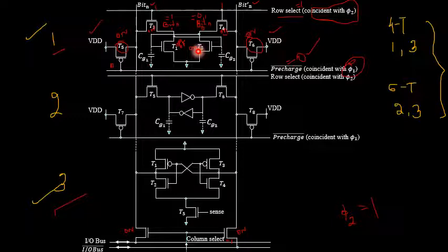The charge will be stored either in the form of capacitor Cg1 or in the form of capacitor Cg2 with respect to the VDD supply rail, such that a 1 will turn off and 0 will turn on either of the transistors. If logical 1 state is stored in the bit n signal, that 1 is going to be applied to these two transistors, right? Because it is having a cross coupling connection. If 1 is applied, this will be turned off. One is the off condition for a PMOSFET, one is the on condition for an NMOSFET.